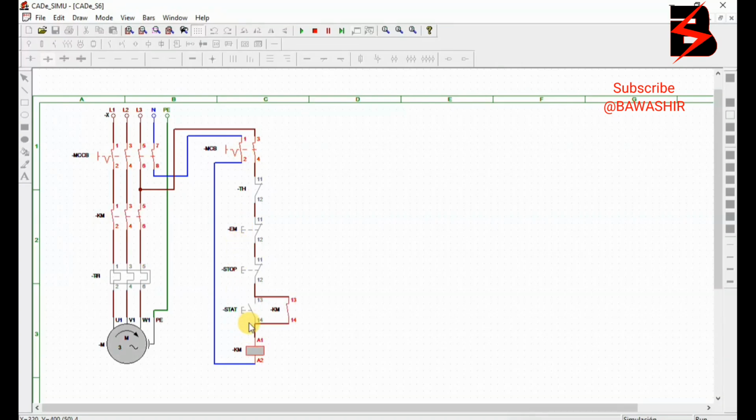You see, once we click start, our motor starts running clockwise. As you see, the coil is energized. The latching contact is still holding the power line to the A1 terminal. When we say stop, it goes off. When we say start, it runs again. So that is briefly how we go about with direct online unidirection. That means a singular direction.